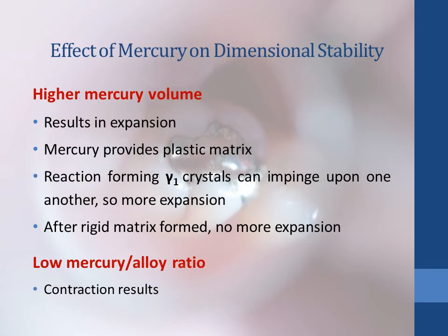And the atomized or the spherical powder. So spherical powders may be of both low or high copper and are produced when all desired elements are melted together. And in molten stage, the metallic ingredients form the desired shape, which are irregular sphere-like structures.